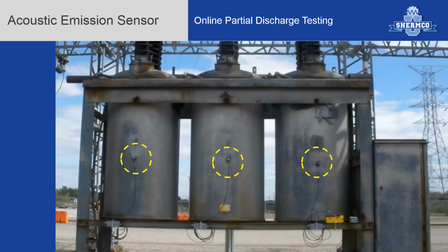Let's talk a little bit about acoustic emission sensors, or contact sensors. These sensors operate in very similar frequency bands as the airborne acoustic sensors, again in the 20 kilohertz out to about maybe the 300 kilohertz realm. The acoustic contact probe is ideal for detecting and localizing partial discharge in fluid dielectrics such as oil or SF6 gas compartments. This is sometimes called in-tank testing.